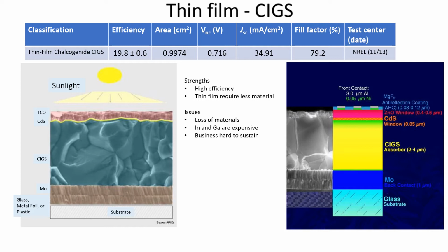The deposition of CIGS films onto a substrate is frequently done in a vacuum by evaporative or sputtering methods. Copper, gallium and indium are deposited first and then annealed with a selenide vapor to give rise to the final CIGS structure.